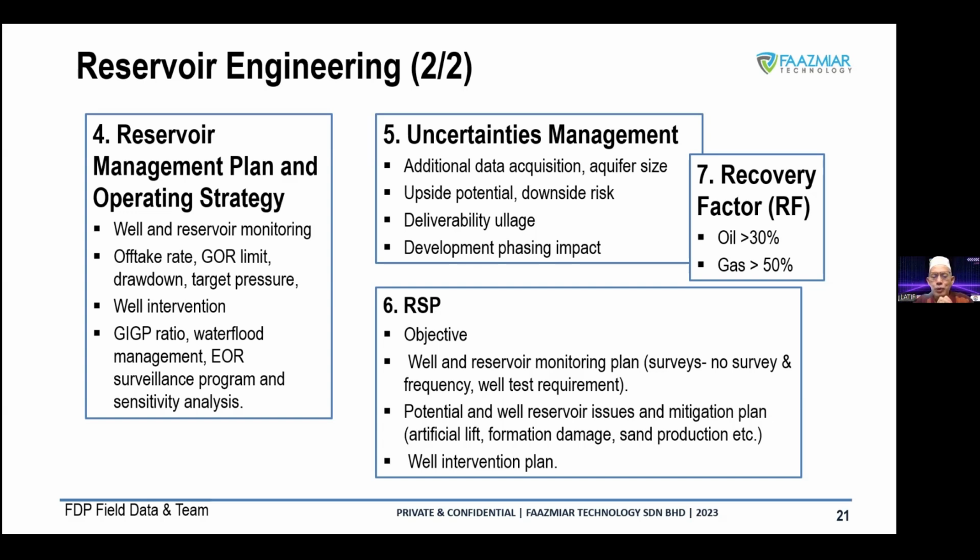This is where they can understand what will happen with the water coming up. For example, if the water coming up is too much, they have to think about installing water removal processing on board itself, because when the water comes in, they have to remove it and have clean oil going through the export line. At the same time, the water must be processed because it has some contamination. They have to clean up the water before disposal to the sea. So all these facilities have to be thought about and put in phases. Sometimes you need this water processing system, sometimes you want to inject water. It's all planned as per the reservoir management, which can tell us when the water is coming out, when the gas is coming out, and so on.